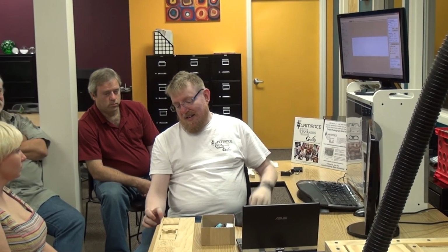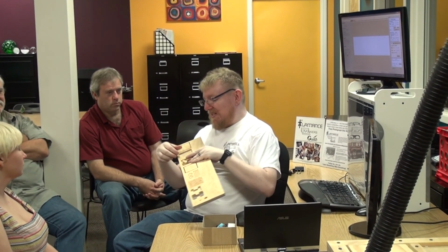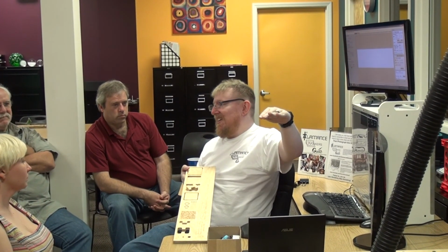So this is 1/2 inch wood. I got a vernier caliper out and measured it. It's 0.498, because that's how deep this piece was sanded, probably. And then that also reflects the humidity today. Tomorrow it might be a little more, a little less. So I'm going to make my file 0.51 so that I guarantee I cut all the way through. Because if you're very conservative about your depth, you'll leave material on the back and you won't cut all the way through, which can be fixed by doing a second pass, or you can trick the 0 and move it down and cut it again.